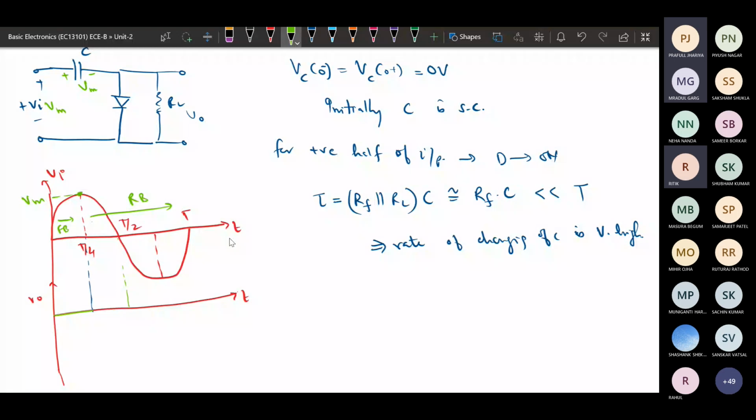But as we decrease the input voltage, the capacitor voltage stays at Vm. The voltage across this diode will not be positive, because it is the capacitor voltage minus the input voltage. The input voltage is now less than Vm, so the overall voltage is negative.